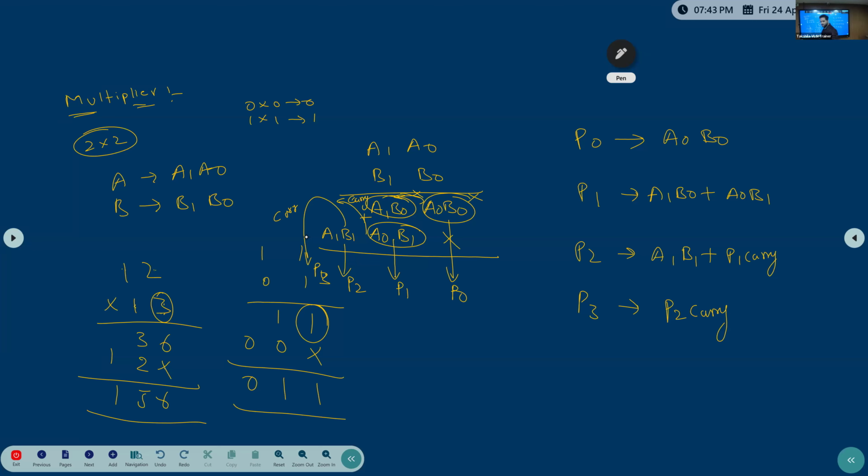If I want to ask in a digital interview how much knowledge that guy has, I can ask this question directly. Many people will fall. Logical addition and binary addition are different. In logical addition, OR gate 1 plus 1, what is the result? 1. In binary addition, 1 plus 1 is 10: sum 0, carry 1.